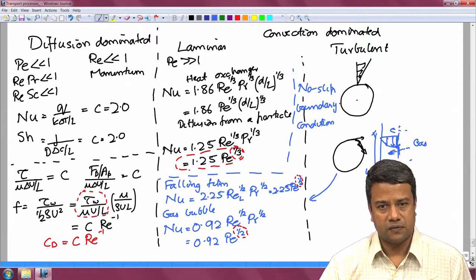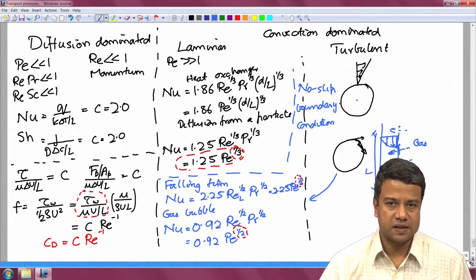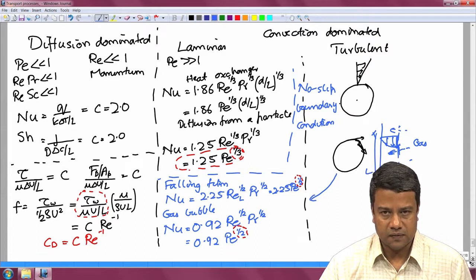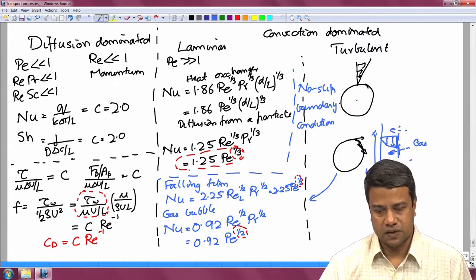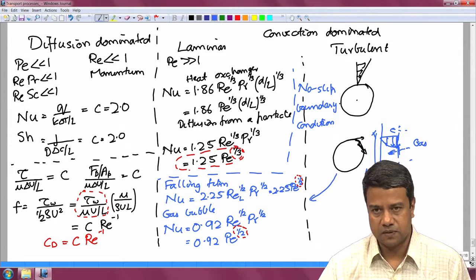Unfortunately, to increase our confusion, usually these momentum transport rates are scaled by inertial scales to get the friction factor and the drag coefficient, and for that reason these things scale as inverse of Reynolds number in the limit as Reynolds number goes to 0.